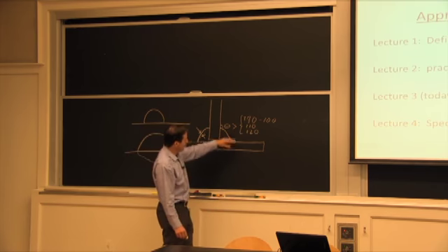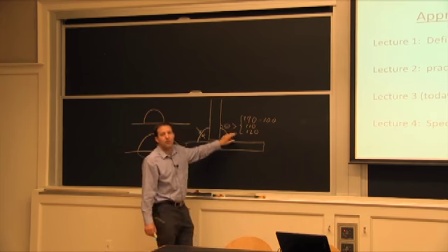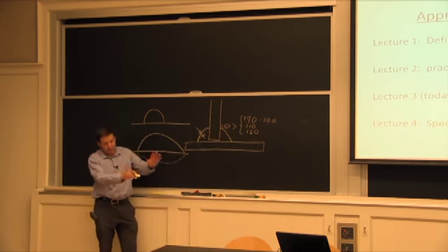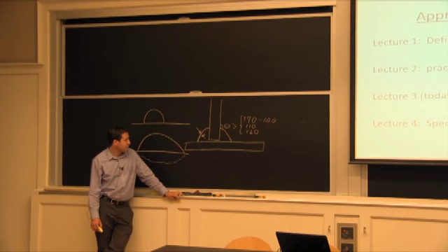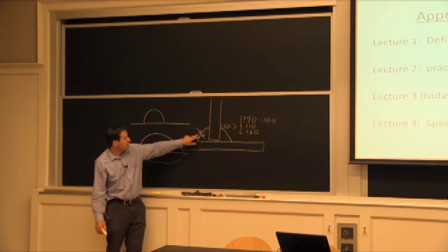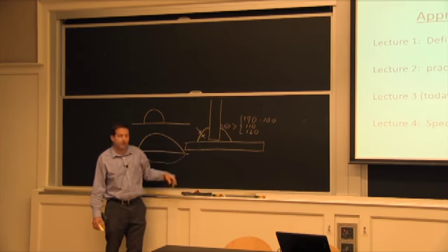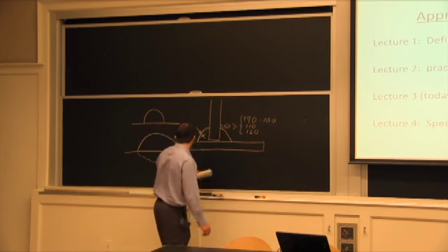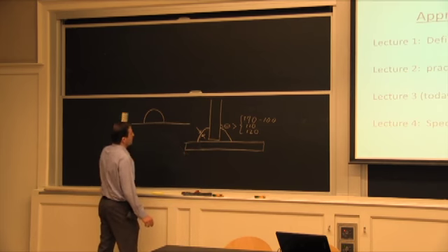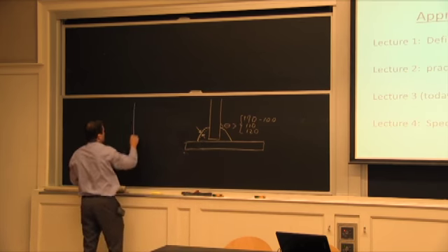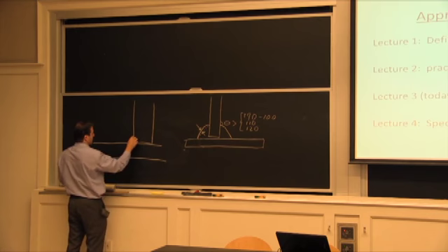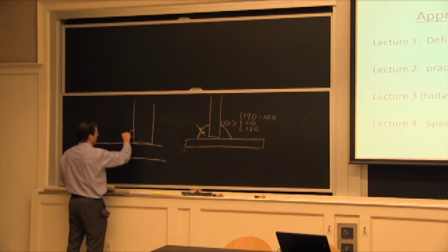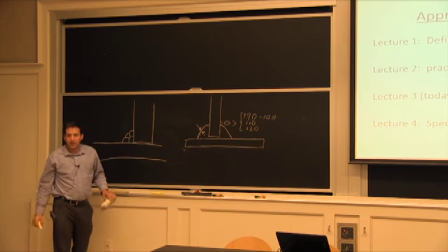In the work I've done going around various structures, I prefer looking at the angle. Maybe because I can figure it out personally better. The issue you have here is if this weld is made out of multiple passes. So if I have, I'm just going to redo this one here, but this time we're going to say it's a bigger member. So somebody came, did the first weld like this, another weld like this, another weld like this. I'm making it up, but you don't have a whole lot of convexity.